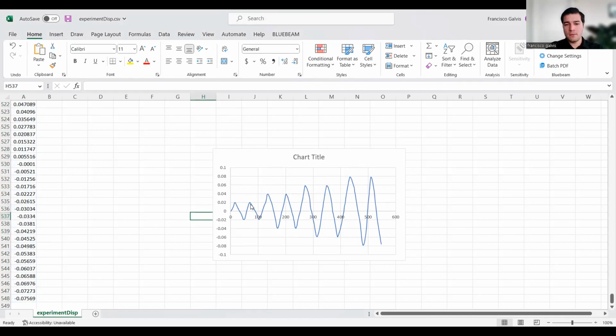So we go from 2 centimeters, 2 cycles, then 4 centimeters, 2 cycles, then 6 centimeters, 2 cycles, and then 8 centimeters, 1.5 cycles. It missed one, the final branch. And that was the test, right? So this is the displacement that was imposed when they were performing the test.